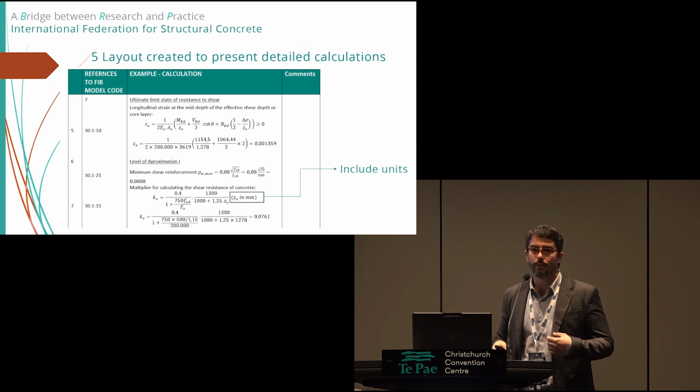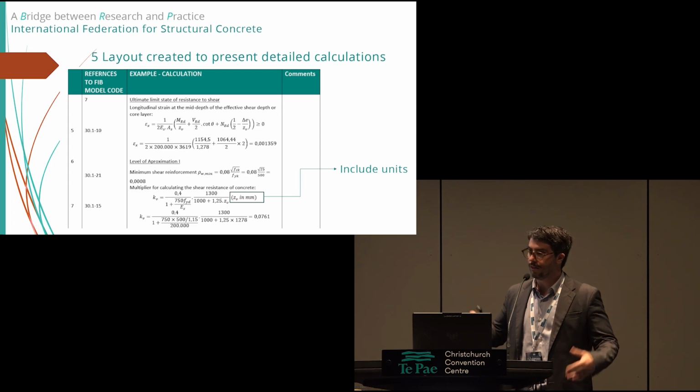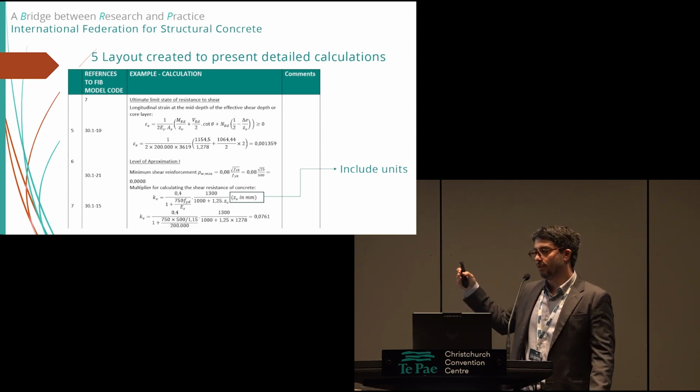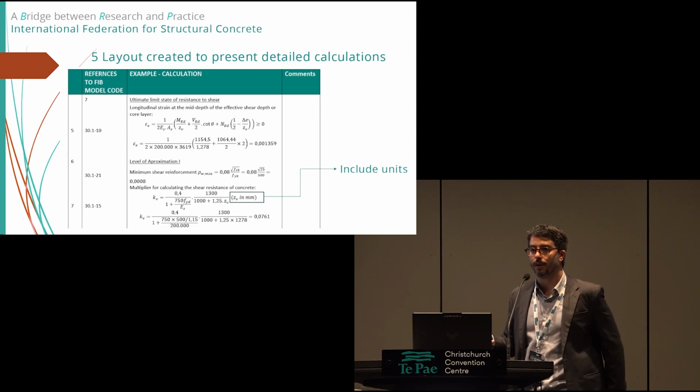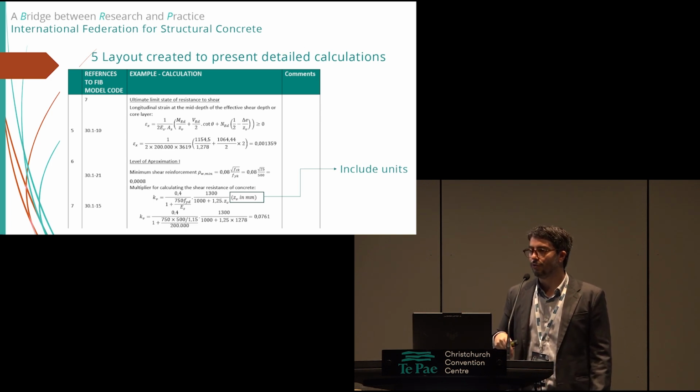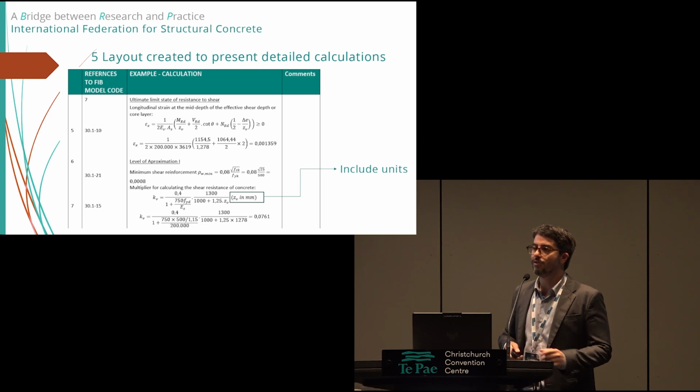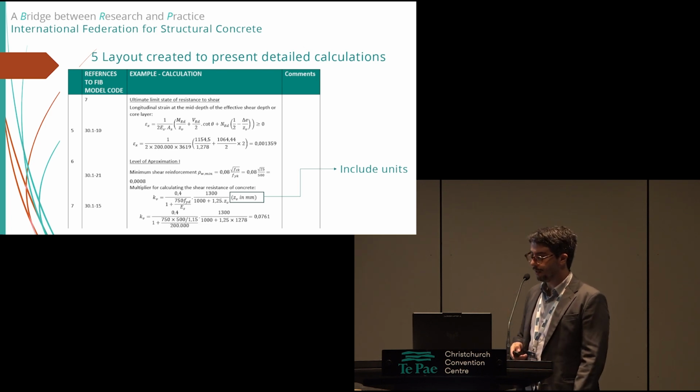Especially for us in America, sometimes we use ACI, and with imperial units, it's a mess if you get it wrong, right. In my country as well, sometimes the technical use tons and the structural use kilonewtons, and we've seen some structural failure because of that. So I think going into details on units is a very important thing.